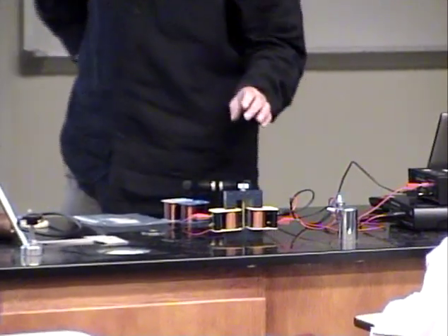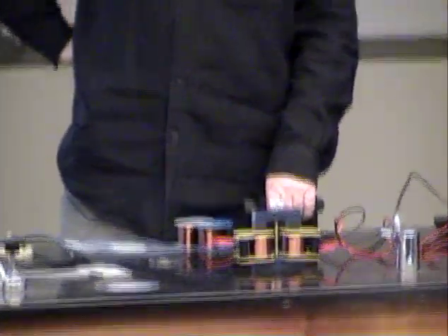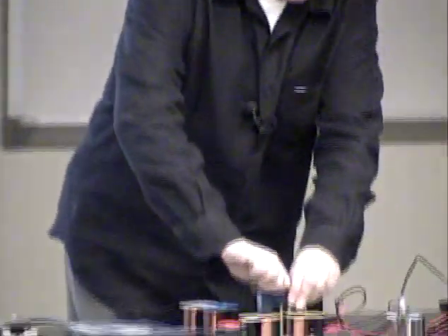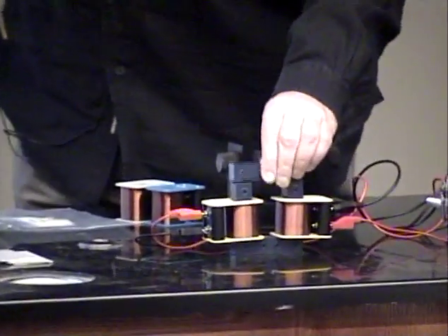Theoretically, if these are identical coils, and if they share exactly the complete flux, what should be the relationship between the voltages? They should be equal, because both are proportional to the rate at which flux is varying. And actually, look what will happen if I reduce sharing that flux.